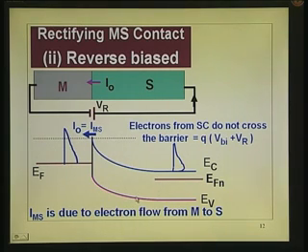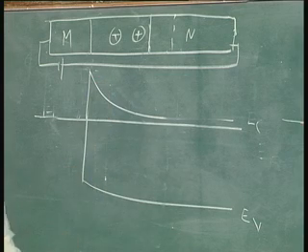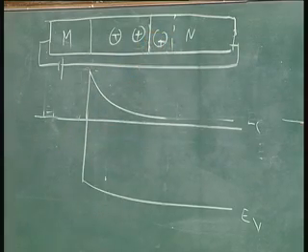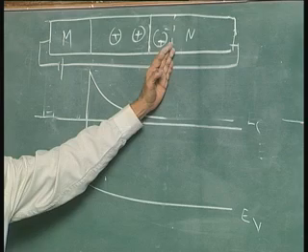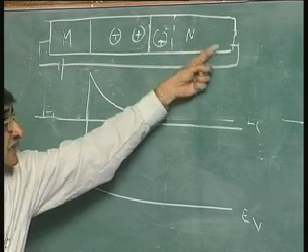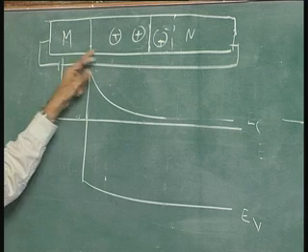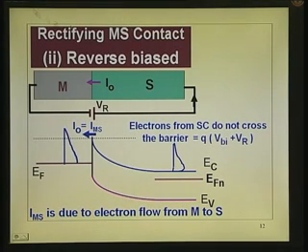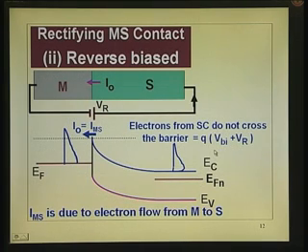Okay. See, what is happening is, the right hand side electrons here have been taken out in this direction. The moment you switch on, there is a transient which will pull from here to here. These electrons will open up, and the depletion layer will widen by removing the electrons from here to that side. When you apply a battery, what do you do? When the depletion layer moves here, you have removed more negative charges from here, and those negative charges have gone through this path to this side. So your field has gone up, the peak field has gone up here, and the potential drop has increased. Okay. I hope I have answered your question. So that is why the potential change from here to here has increased. What was originally the potential QVBI has now become equal to QVBI plus VR. VR is the applied voltage.